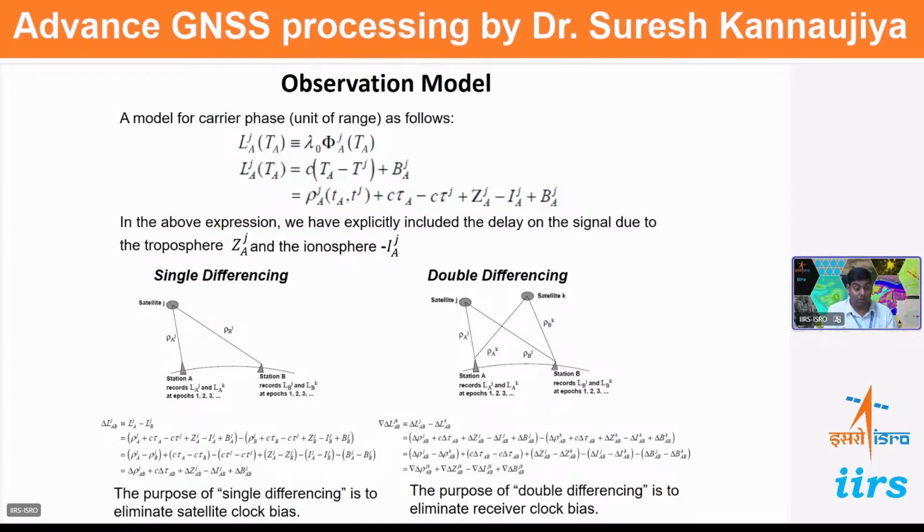So when we are able to estimate the almost true range between the satellite and antenna, then we can think of millimeter accuracy estimates through the fundamental equation. This is the formula we use to calculate the length between the satellite and antenna. After removing the ionosphere, troposphere, different error budget, and time delay, we can think of an accurate length estimate.